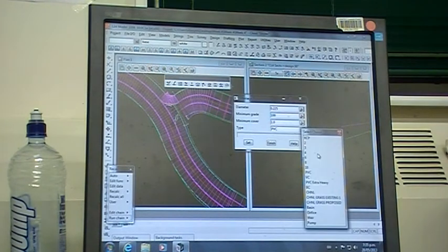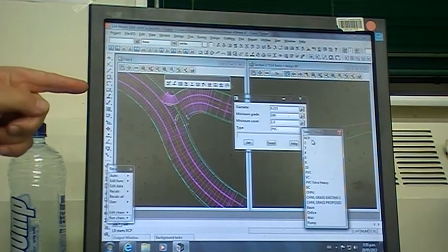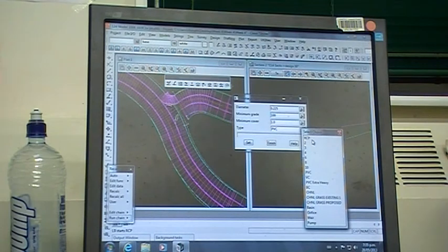And the pipe type, there's a couple of different ways of expressing these. The top one here, RCP, is a reinforced concrete pipe. When you look through standards, a lot of the standards in Auckland still will have RC, RRJ, and then a letter. Reinforced concrete rubber ring joint, which is the standard stormwater pipe. They used to be class XYZ. They're now class 2, 3, 4.